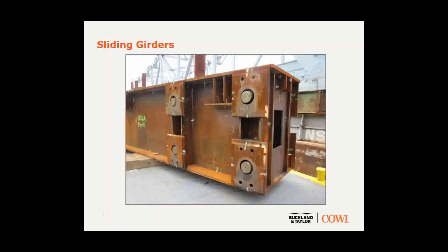We had to pre-install the sliding girders up in the air, and you'll see this coming up, position them, and then raise our truss past the whole pier cap, and then bring the sliding girder in, position it next to the tying girders, and then draw these pins out into the tying girders, basically to make the biggest moment connection that I ever designed, and allow it to function as a continuous beam.